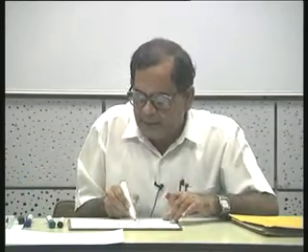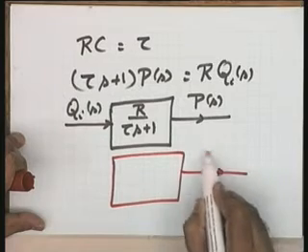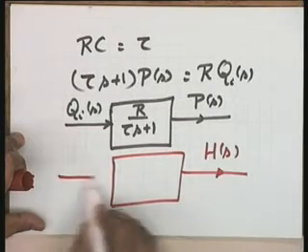Okay. So in this case, as I said, the control variable is mostly the height of the liquid in the tank and not pressure. Pressure we have taken as the variable to develop a suitable analog with electrical systems, or to write the parameters, the resistance and the capacitance parameters of the system. Come on, make a quick change. Give me a change in this particular block diagram when I want the height H(s) as the output variable.